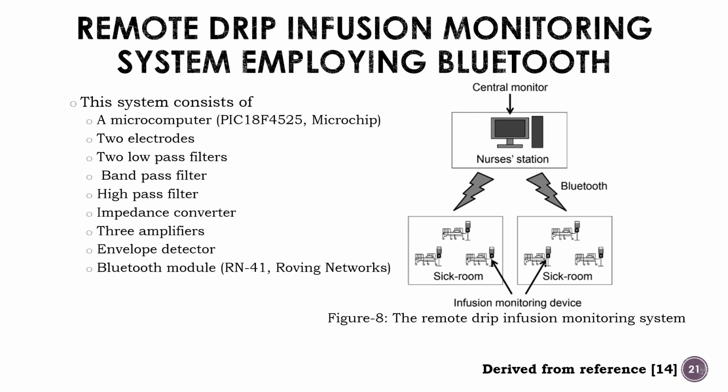The signal that passes through the band pass filter is amplified by the second amplifier by 36 dB and can be demodulated by the envelope detector. The envelope detector demodulates the signal that has been modulated by the rise and fall of each infusion drop. Other electrical devices interfere with the demodulated signal, and the signal is fed into the 16 Hz low pass filter to remove the noises.